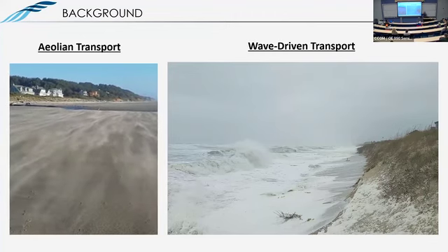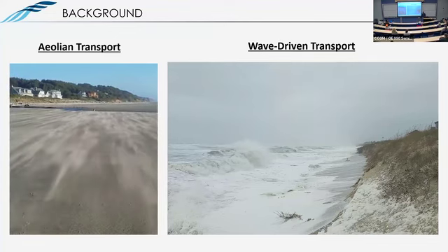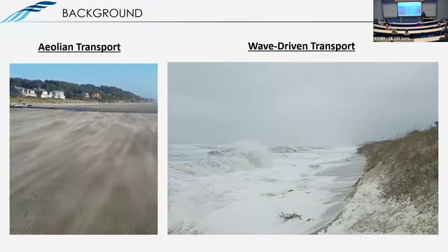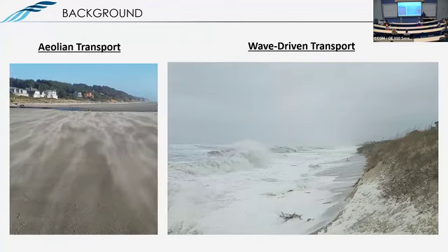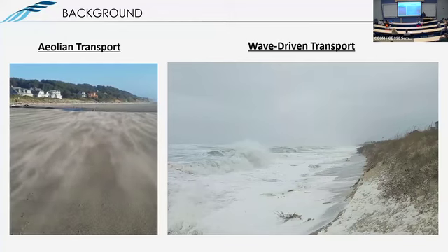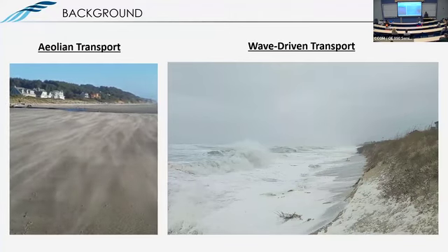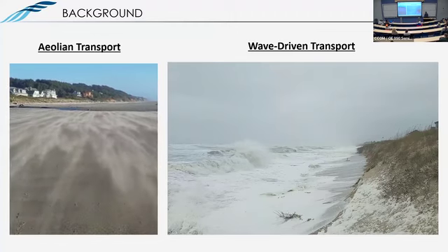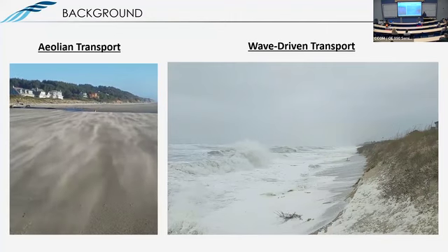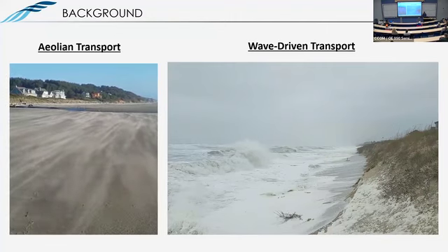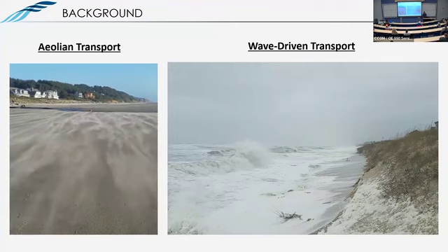If you were dealing with systems like this in the continental US, snow and iced-over conditions can really quickly shut off wind-driven sediment transport because moisture plays a big role in that. You just have no sediment supply if you're covered in snow and ice. Undoubtedly it's going to have the same effect on wave-driven processes, except that you could imagine a case where waves are not frozen and could glide over the beach, and maybe there's the potential that it exacerbates erosion in certain locations, just changing where sediment is sourced from.